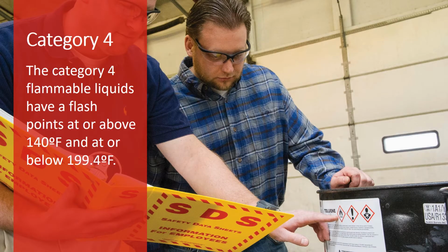Category 4, having flash points at or above 140 degrees Fahrenheit and at or below 199.4 degrees Fahrenheit. When a liquid with a flash point greater than 199.4 degrees Fahrenheit is heated to use within 30 degrees of its flash point, handle it as a category 4 flammable liquid. An example of category 4 flammable liquids is diesel or fuel oil.